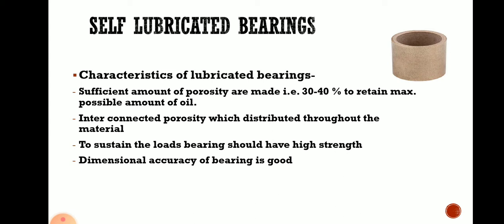Again, the porosity is inversely proportional to strength. So such bearings have more oil retaining capacity but less load carrying capacity. So these bearings have a lower load carrying capacity, but they work well at very high speed, isn't it? Those are some characteristics of the bearing.